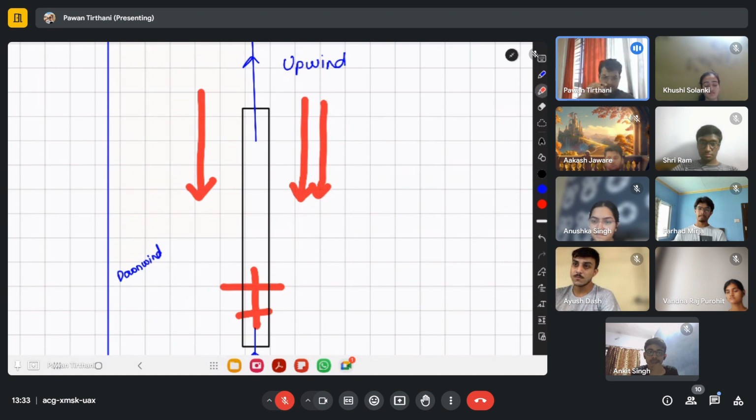So when I am standing at zero speed, I am getting an airflow of 20 because of winds. Now if I'm on the ground at a speed of 20, 30 knots, I'm getting over my wings a speed of 50 knots. So cool, right? So I can take off earlier. That is the reason why we always take off into the wind.